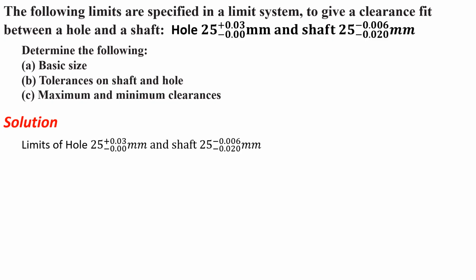So here, given data, limits are given. The limits of the hole are 25 +0.032/-0.00 mm and the shaft 25 -0.006/-0.020 mm.